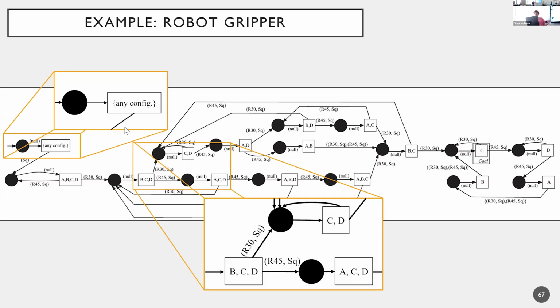This is nice that we can do it without any sensors, but it requires that the robot execute this entire sequence of actions every single time it wants to move a part into a known configuration. It also requires storing this entire sequence and remembering where you are in it while you're doing it. And if anything moves the part during your execution, the robot has no way to tell, and it just has to start over again, which isn't very nice.